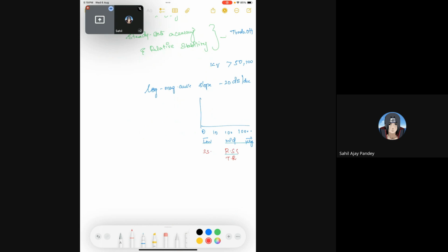And in the further range, that is the high frequency range, if the gain you have in this region is of very high magnitude, then you need to attenuate this gain so that you will get a noise free system. Otherwise this will increase the noise or the disturbance in your system. So when you want to fine tune your steady state response, you will look in the low frequency region. So how can you design a compensator so that you can adjust the Bode magnitude plot of your system high or low or shift towards left or right so that I can get the desired steady state response.